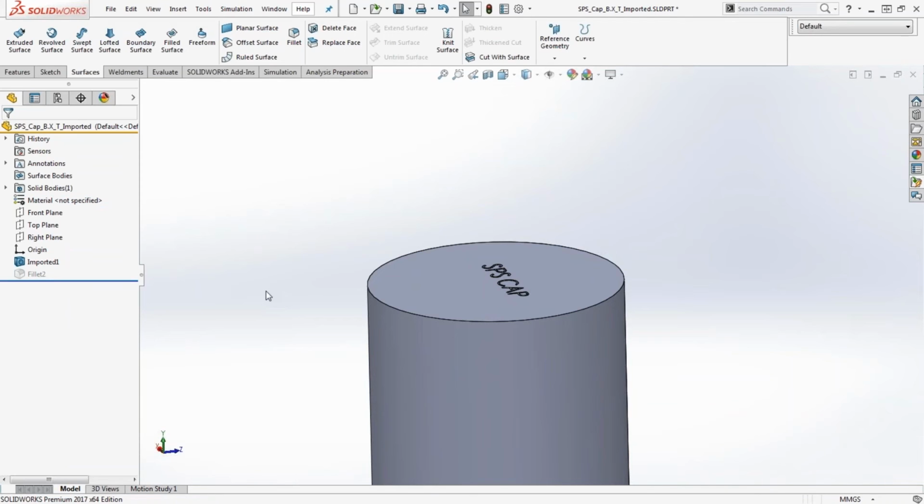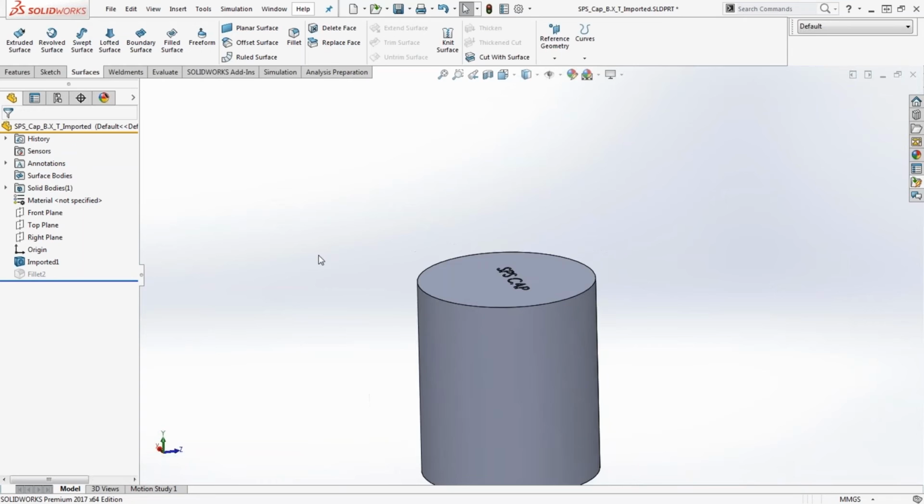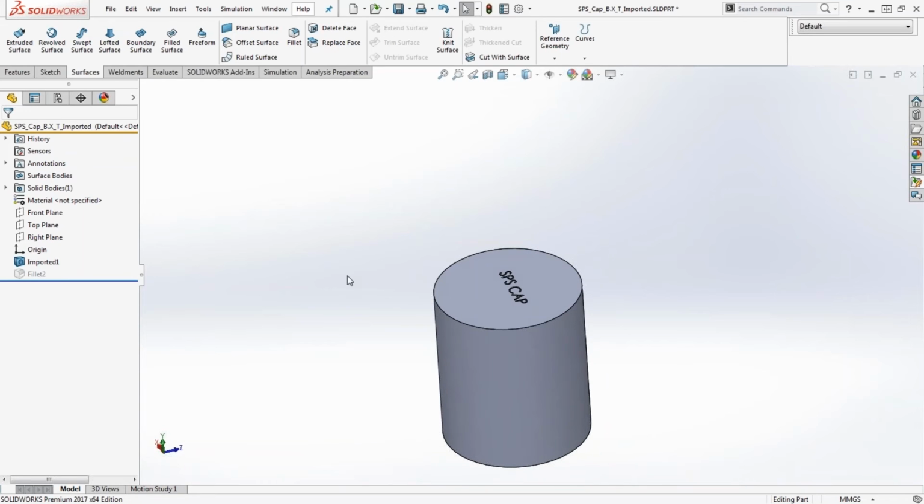It's a lot easier when you're editing a feature in a simplified case, like a fillet. If you have holes, you can right-click on the hole and it will create a Hole Wizard as well, so you can adjust those components. So you can directly edit on a feature-by-feature level, and it'll hopefully create that feature where it's editable, or you can just get rid of it, right?